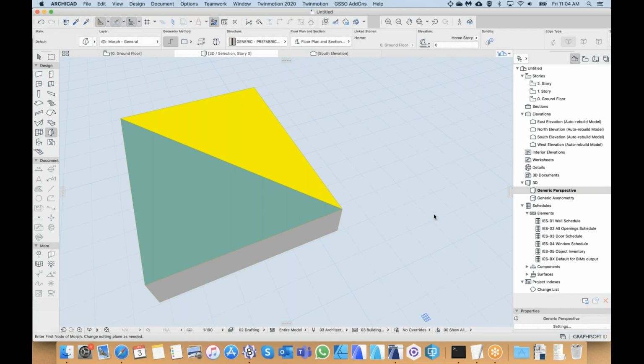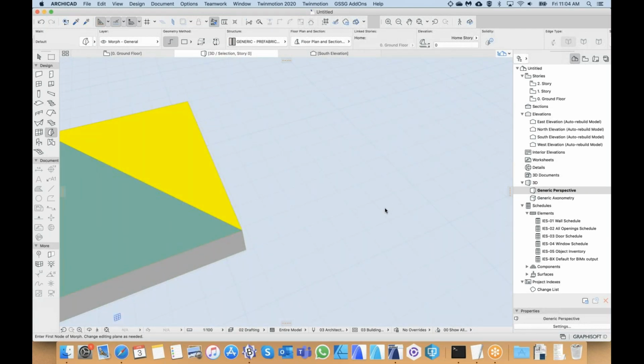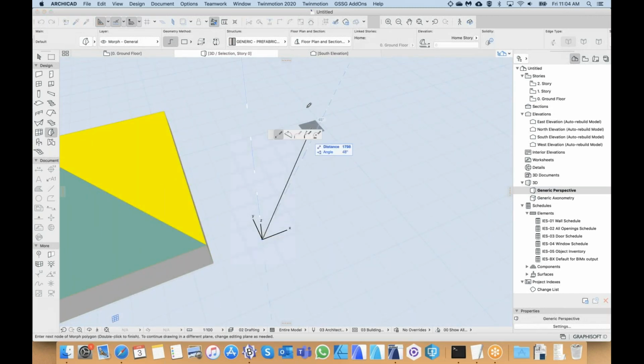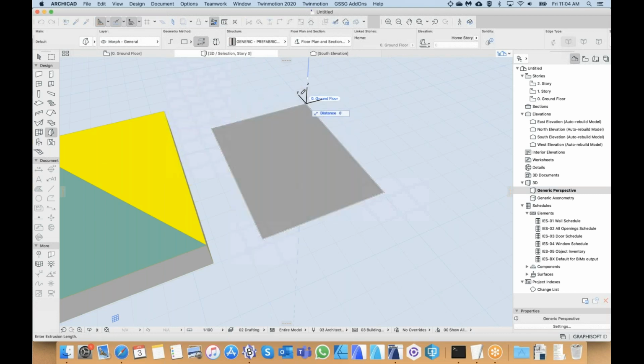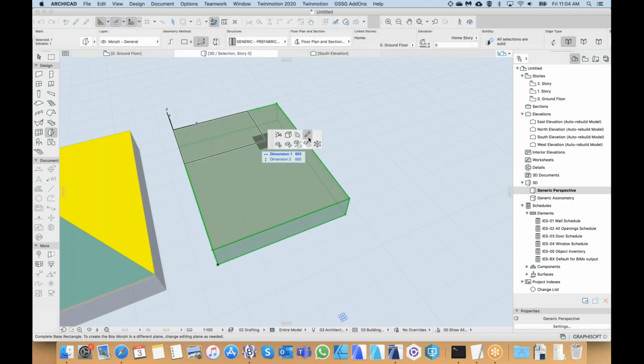My pencil toolbox is floating, just because you're inside the editing. So one person asked, my pencil toolbox is floating. So again, I'll show you. The Morph toolbox has two layers. So if you see this layer, then it means that I'm in editing or drawing mode.